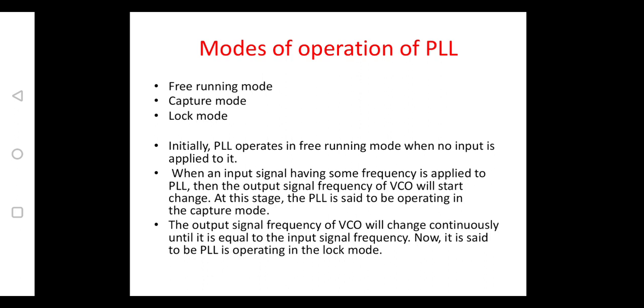The last mode is lock mode, in which the output signal frequency of the VCO changes continuously until it becomes equivalent to the input. When the input signal frequency is equivalent to the VCO signal frequency, only then is the PLL said to be in lock range.